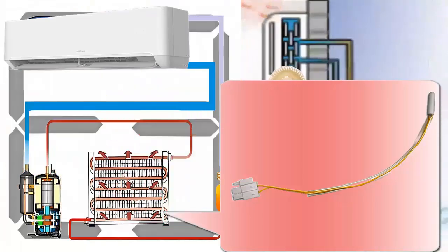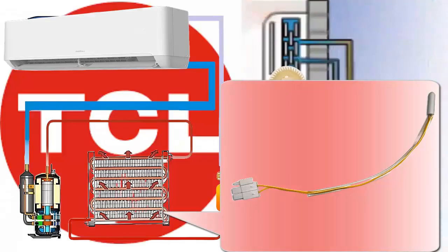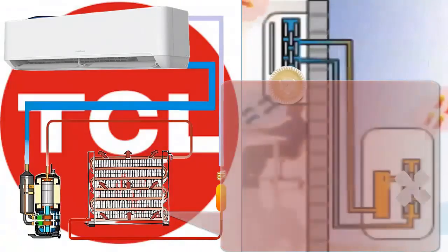Additionally, this temperature value allows the controller to calculate the gas pressure, estimate possible subcooling values of the refrigerant in this part of the cycle, and ensure that the system is operating within a safe range for the compressor.